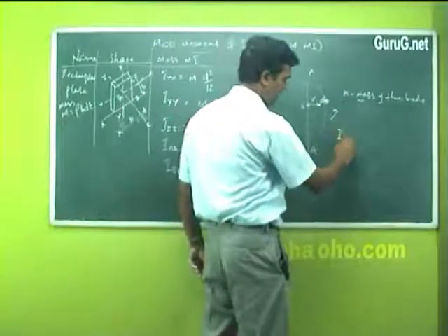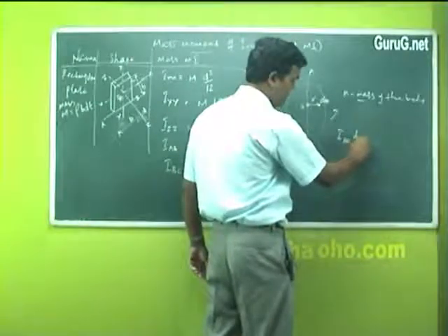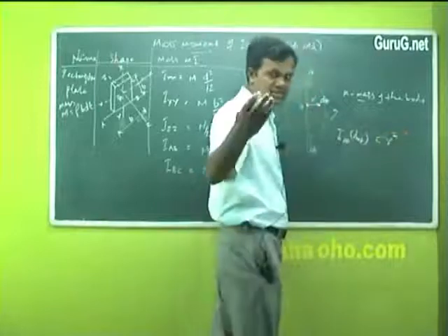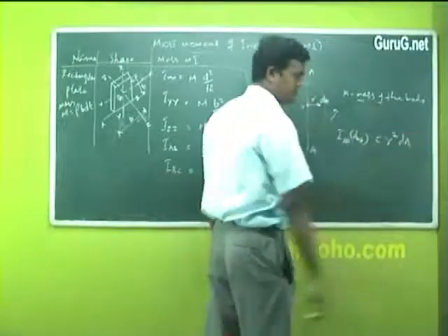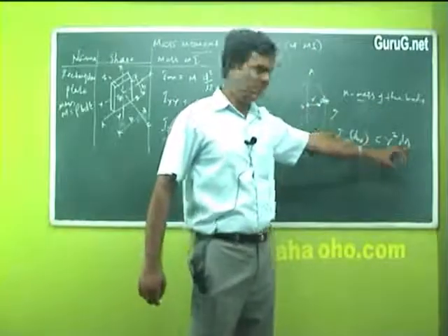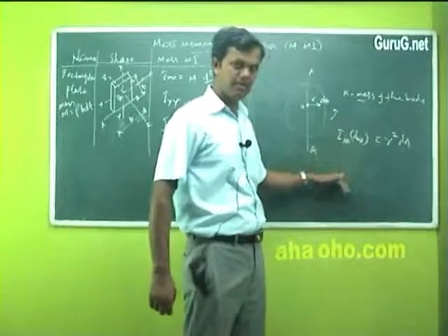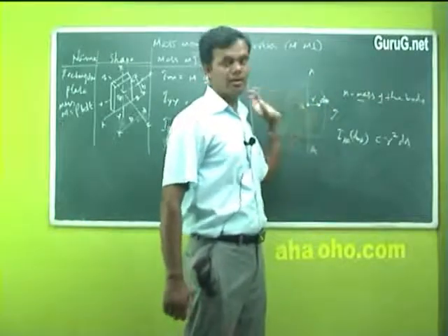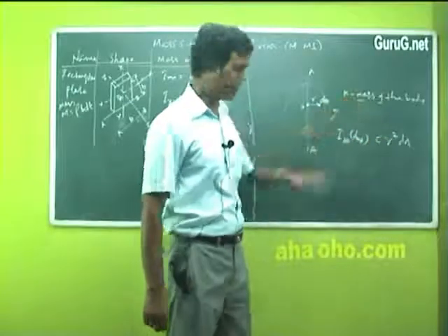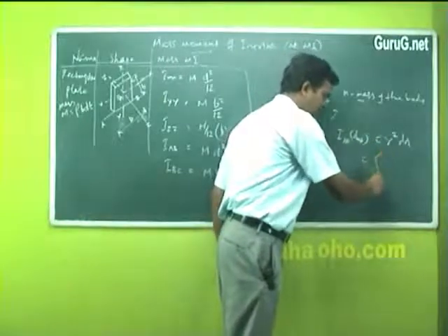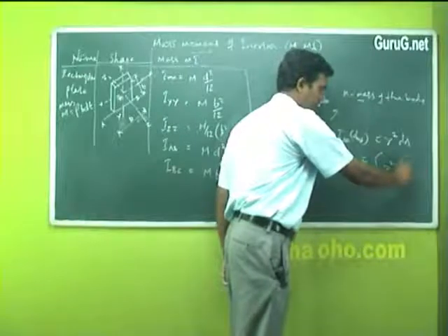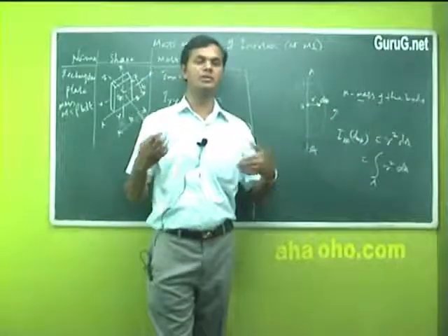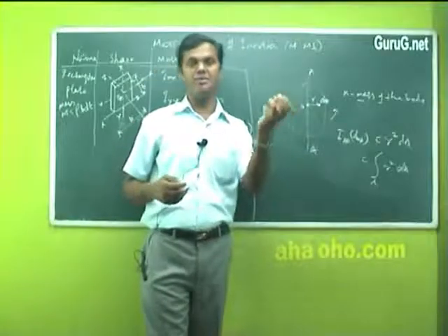That is given as I of AA, the mass moment of inertia, which is r squared into dm. The meaning is that a small element is assumed to be rotated by fixing the axis AA constantly with the radius of r. The square is written because it is the second moment. Finally, this will be integration over the total mass, r squared dm. This is basically called the mass moment of inertia. The purpose is to find the moment of inertia of an element with a mass m.